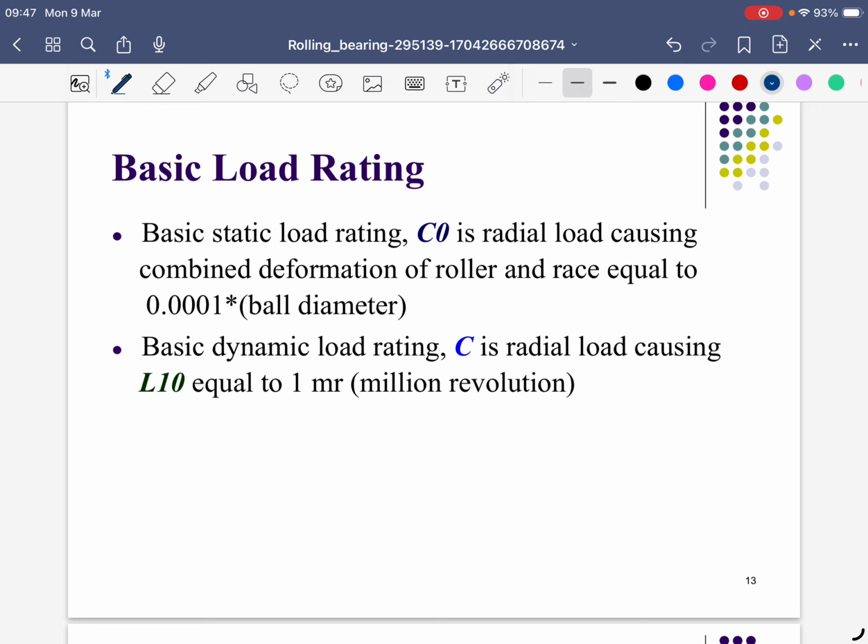So if this turbine does not rotate, what happens? It means that the contact point will always be the same point. So they do the rotation. That means they try to distribute the contact point to all the elements, and then they reduce the risk of permanent deformation.